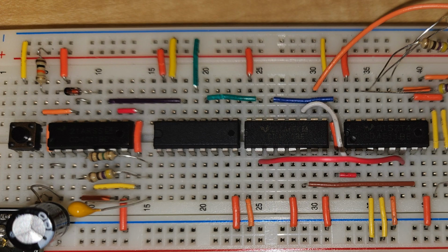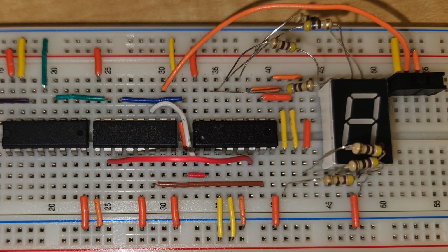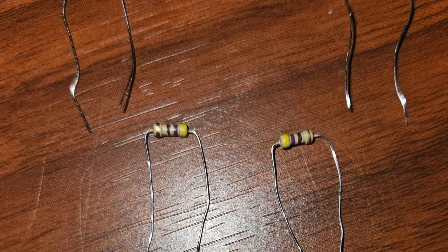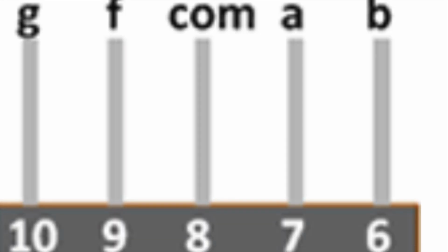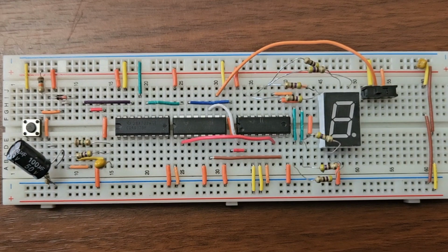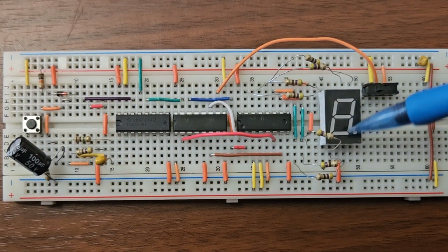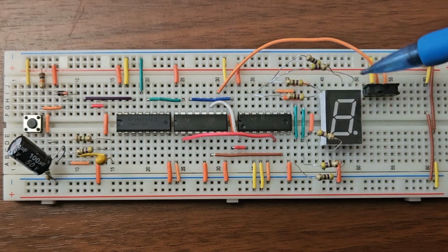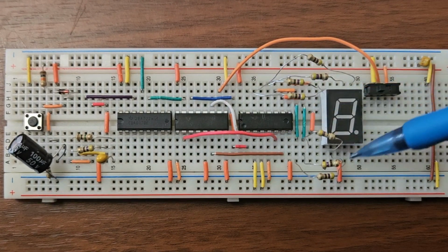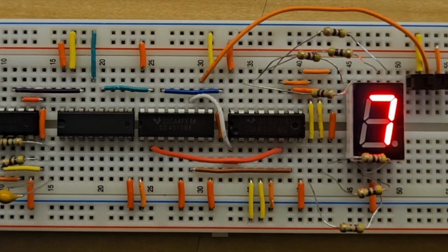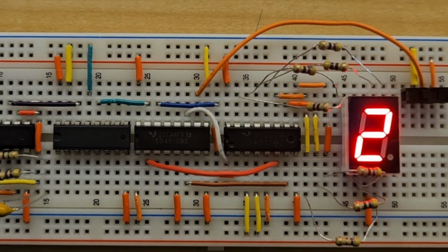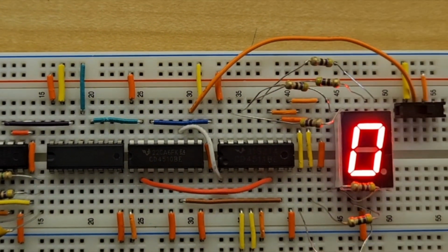The counting circuit prototype's final step is adding a 7-segment display alongside 7 470 ohm resistors. The 7-segment display has 10 pins. 7 of its pins are labeled letters between A and G. The display has 7 built-in LEDs. Each letter is connected to the corresponding letter on the 4511 using 470 ohm resistors. The resistor ensures that the display does not short and that the LEDs are not too bright. The numbers are displayed in Arabic numerals.